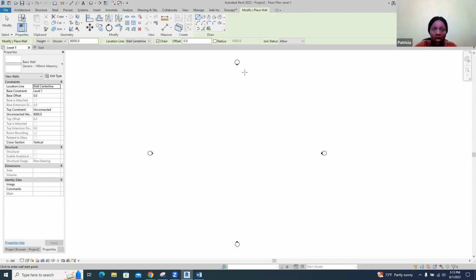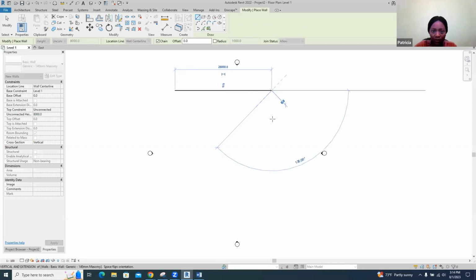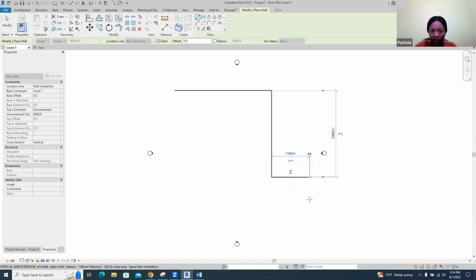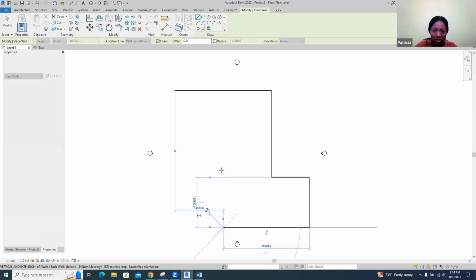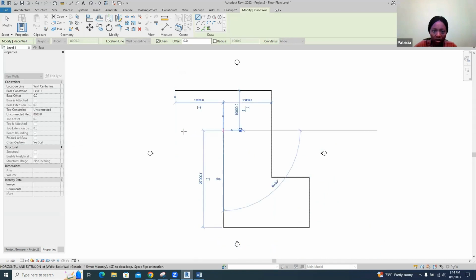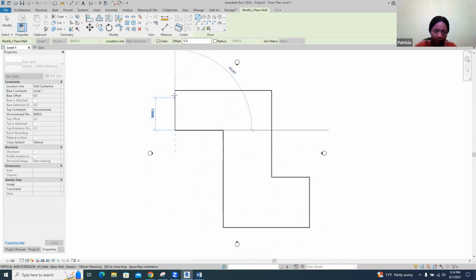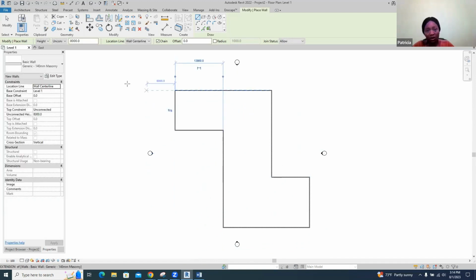140 masonry. Once we select the type of wall we want, we can go to this modify tab and say we're drawing with a line or rectangle. So let's try to draw the one that we just saw, let's call it L shape or S. Okay, so we had it moving like this, and it always shows you when it's straight with the blue lines. And so we have this shape that we had in the drawing.